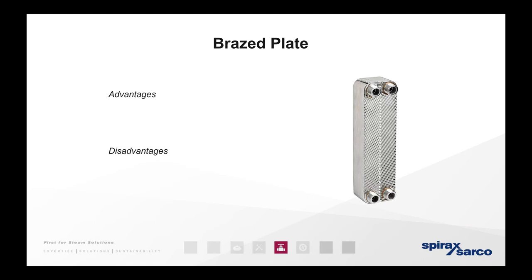Another question, yeah. What factors should be considered when selecting the material and configuration of the plates in the plate and frame heat exchanger for a specific application? So mostly steam is sterile. It doesn't tend to carry anything. When you're talking about the quality of your steam, it's the particles you may have hanging in it. So trapping, strainers, things like that before. You want the quality of your steam as high as possible.